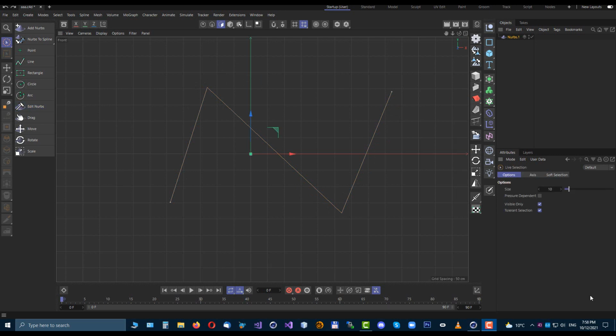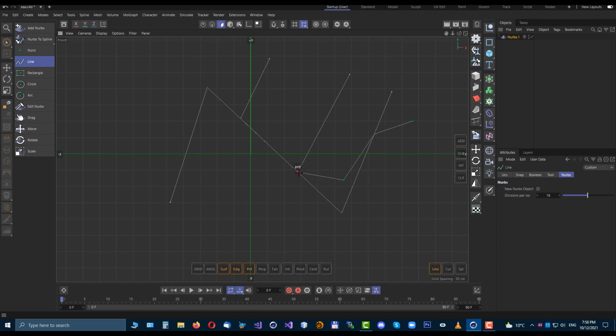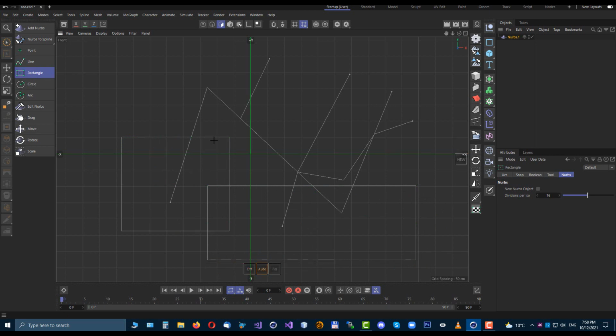Very easy. And finally I'll show you some more complex object. Let's add some polyline with overlapping parts here, because regular floor plans are not this simple, are not that clean. You always need to do some additional cleaning and modifying redundant things. So let's do the join and explode on this object. So first I will explode everything. Everything is exploded, and now I will join it.